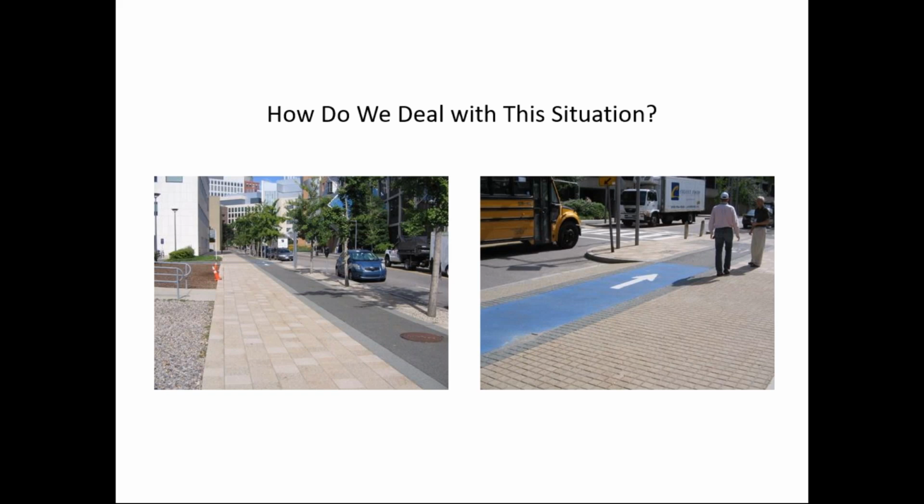It looks very nice, but not to criticize it, one of the issues here is that this is really a violation of ADA subpart E, if you remember yesterday, which relates to communication. A sighted person can tell visually through the color differences that we have two separate facilities here, but that information is not communicated to a blind pedestrian because they can't see that color differential. So from an accessibility and especially a safety standpoint, the question is, how do we designate detectably so that someone with a cane can tell the bike facility from the pedestrian facility? That's what I'd like to talk about briefly.